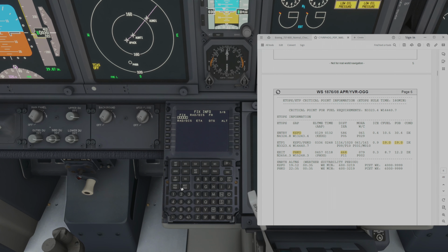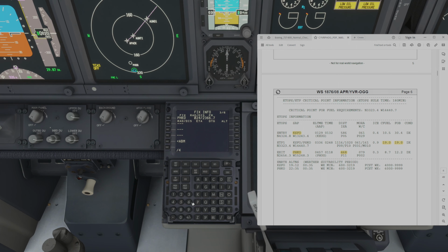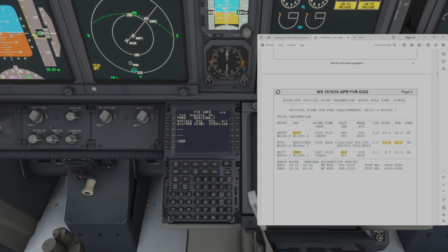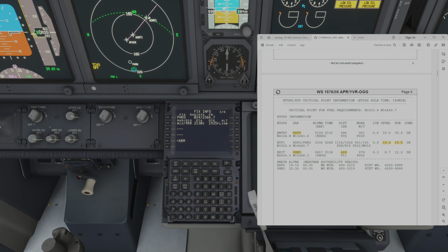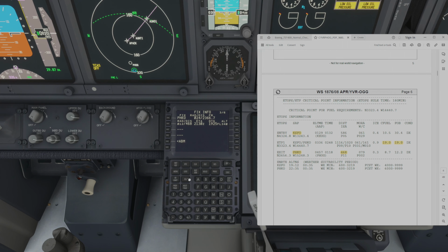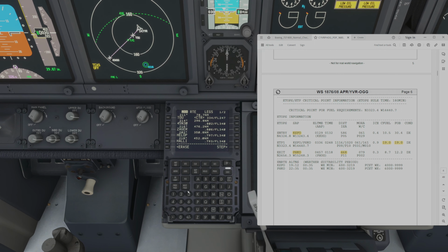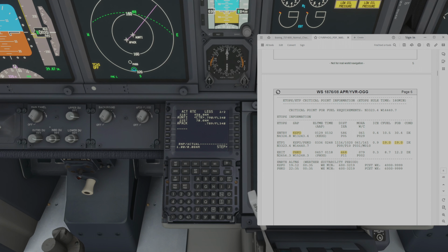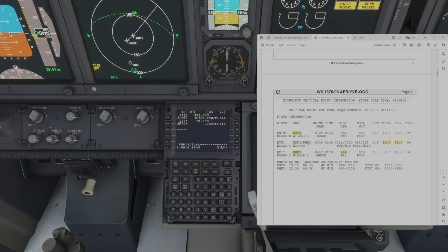So PHKO and slash 468, and that's giving us the exact radius. So we didn't really have to add the exit point there, so we can actually go ahead and delete that. Alright, so we have our ETOPS entry, critical point, and our exit, ETOPS exit set up on our ND.